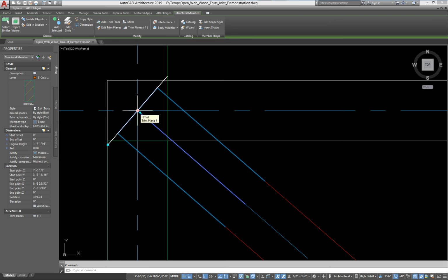And I'm going to drag, there's 2 icons here, or 2 little grip marks. I want the one that moves it, not the offset one, so just make sure you get that. And then bring that down to where you want to locate it. And make sure, again, down here that you've got your Z locked on. And I'm going to go ahead and bring it to right here. And then I'm going to bring the rotation to right here. So now I've trimmed that structural member horizontally.